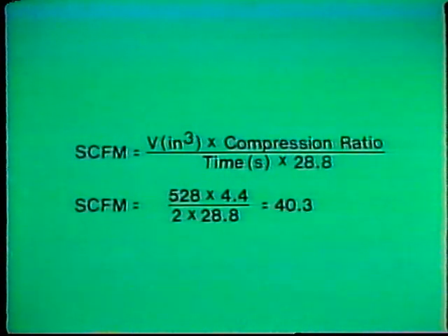Well, you can see that it's important to use the right cylinder in pneumatic applications, and that it involves more than just picking one off the shelf. Often you must consider stop tubes, rod diameters, and cushion ratings to be sure you've chosen the right one. And the system has to provide enough air at the right pressure to enable the cylinder to do its job.